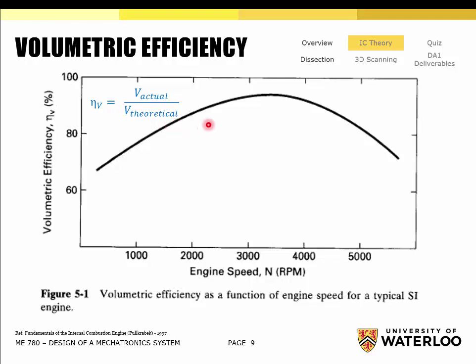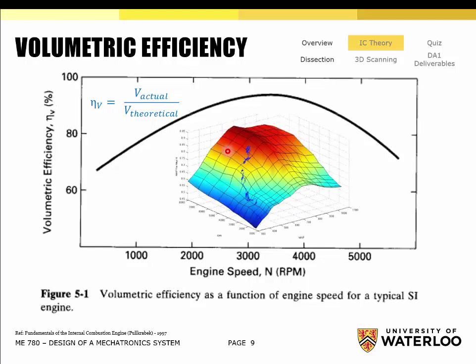So you can see that depending on the angular frequency that the engine's operating at, you might have an optimum peak that you want to operate the engine at. In the way that the computers are controlling the actual engine control unit, you might have a map of a few performance metrics. This 3-dimensional map has engine speed on one axis, engine load or throttle position on the other axis, and volumetric efficiency on the z-axis. So this is effectively a model of the breathing behavior of the engine over all of its operating range, every angular frequency and every throttle position that the user is commanding.